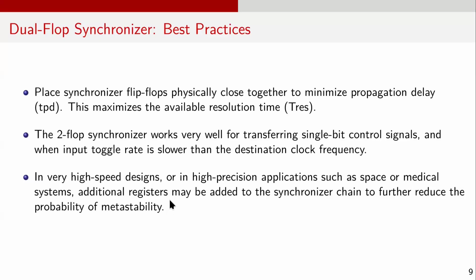In very high speed designs or in high precision applications such as space or medical systems, additional registers, maybe 3 to 4, are added to the synchronizer chain in order to further reduce the probability of metastability. This concludes our discussion on the dual flop synchronizer.